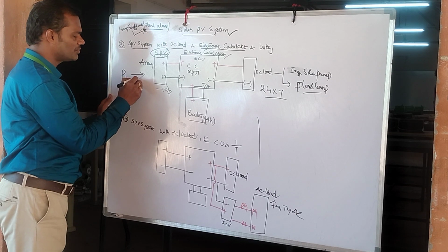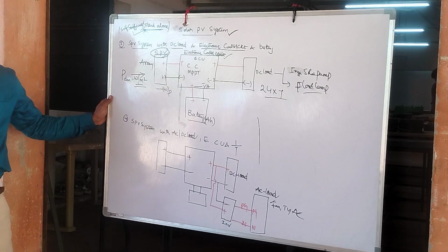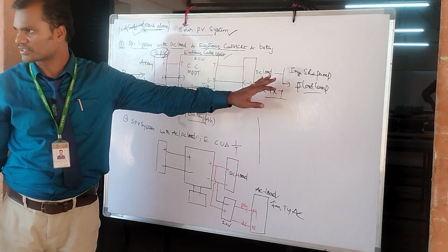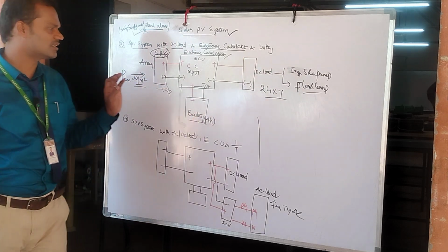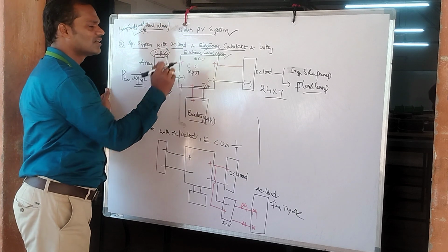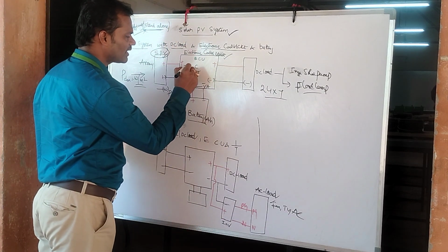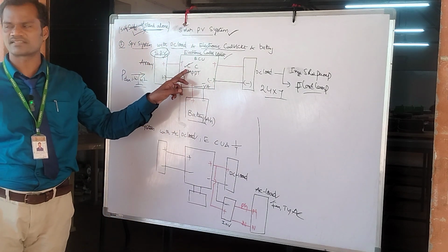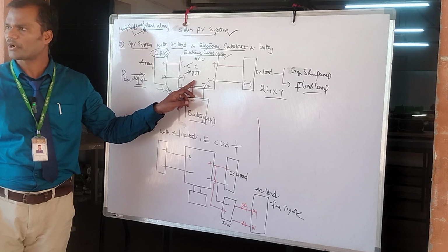The power density unit is watt per meter square, 1000 watt per meter square. The power density is varying, but the load should not have those variations. The load should happily run with the required speed. If you want it like this, then you require an electronic control circuit which takes care of it. Indirectly you are going to have two internal parts in it, where the first one is called a charge controller and the next one is called maximum power point tracking.